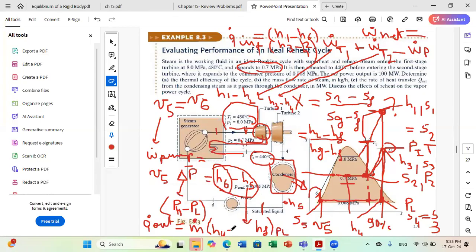If they ask you, how can I improve the thermal efficiency of this system? You can say, I can do heat recovery and profit from Q dot out. So if I have a high efficient heat exchanger, let's say a heat exchanger of efficiency 90%, so 90% of the heat rejected will be used, for example, to heat a certain fluid.